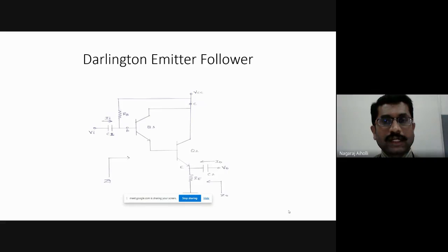We are discussing the Darlington emitter follower. This circuit is the same as the normal emitter follower, but here we have two transistors instead of a single transistor, connected in a Darlington fashion. That is, the emitter is connected to the base of the second transistor, and the collectors of both transistors are shorted. The output at the emitter follows the input at the base. This is the Darlington emitter follower circuit.